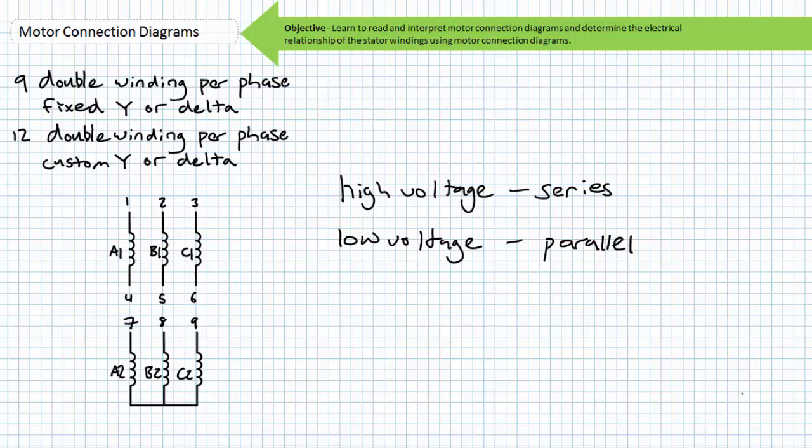This is to suggest that given a choice, the higher voltage, lower current configuration may be preferred given the cost per foot of thicker gauge wire necessary to run the lower voltage configuration. Regardless, the electrical power consumption and the mechanical power delivered should be the same for either configuration.